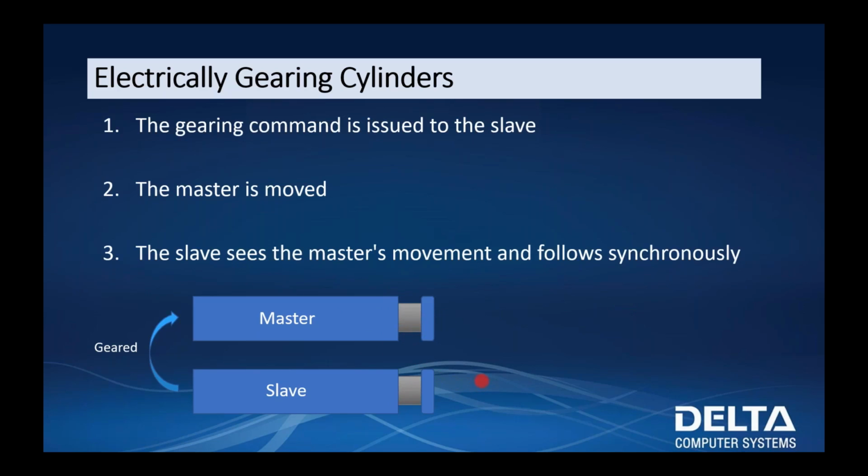So how I have this one geared up right now is not just a one-to-one, right? For a one-to-one, you probably just want to use the move absolute command. This is slightly different. I can see as my cylinders move out, they hit their endpoints at the same time, but it's not quite a one-to-one ratio. Maybe it's more like 2/3 of the full extension here. So this is a perfect example of where gearing can be very helpful.